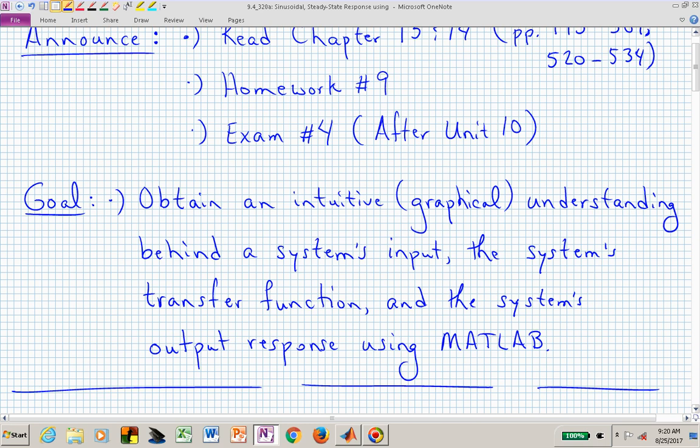We can go into the frequency domain, multiply the transfer function times the Laplace transform of the input waveform signal, and that will produce the Laplace transform of the output signal. We can inverse Laplace transform that output signal's Laplace transform and obtain the time domain response, which is what we will see at the output from that particular system's transfer function.